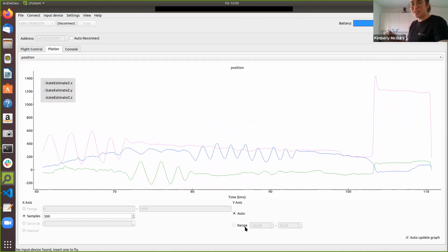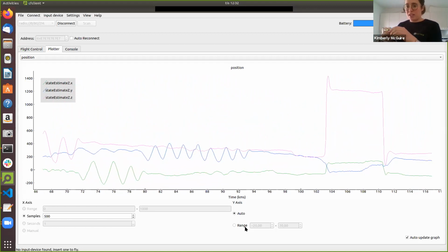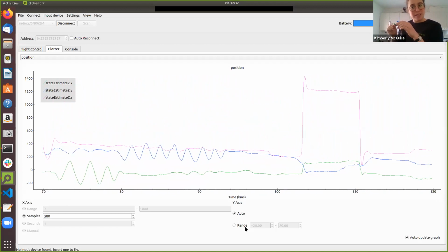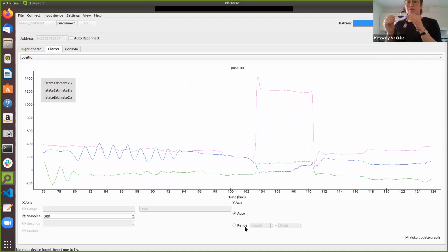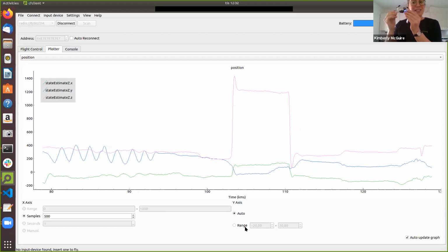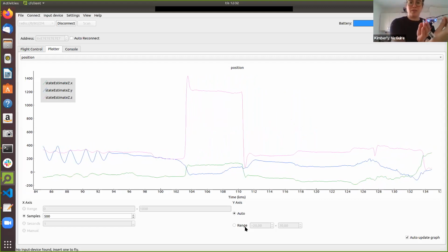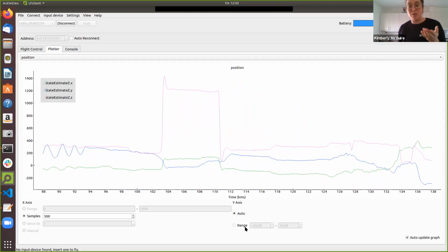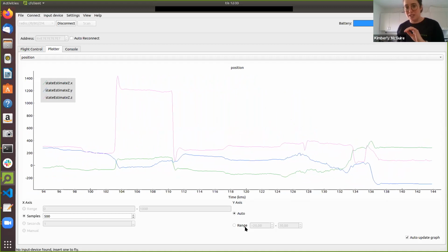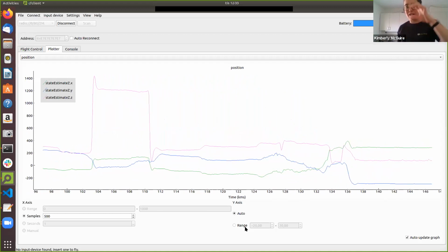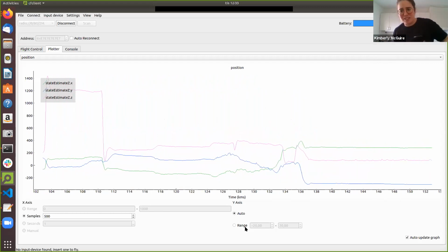All right, there is a question. Can you do circles, let's say, with the Flowdeck? Do you mean that, Dario? Yes, you can. So you can give it a command to rotate. You just have to do it slowly. If you do it too fast, it will drift. If you can fly like a circle, that is actually what I would say: if you want your Crazyflie to move, always do that as a circle, because then it also gets some forward flow as well. I did it also during my research. That worked much better than having the Crazyflie just fly at a certain position and rotate. Dario, does that answer your question?